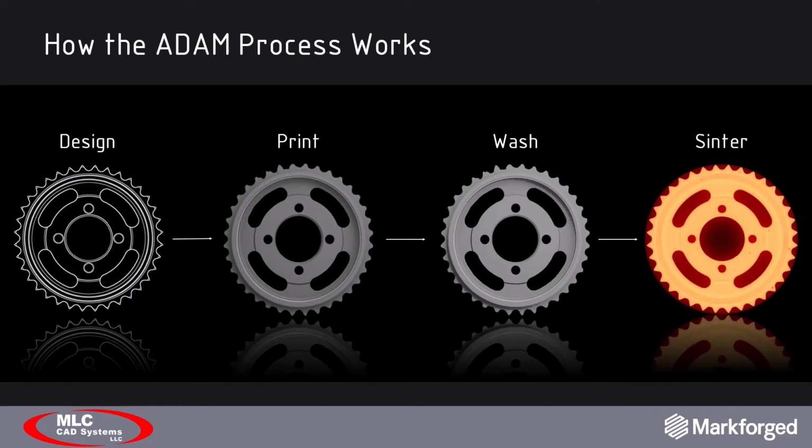So how does this add-on process work? One of the big reasons that Acme Audio went with the Markforged printing was that it was simple. So they're obviously leveraging SolidWorks. They design a part, in this case their heat sink. Then they simply export that as an STL and send it into the Markforged slicing software, which is called Eiger. That prepares the STL file and it prints it directly inside the metal printer.